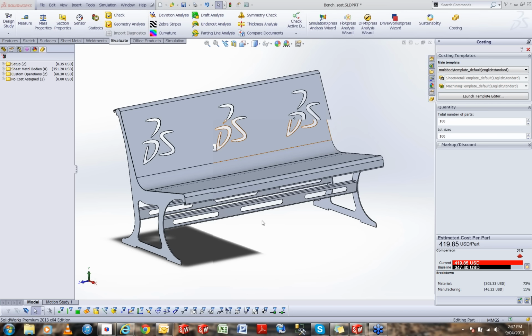So we've got a question: is the size of a design piece limited by the environment of the complete drawing? I'll take that to mean how big can you show the views on the drawing. I hope that's correct. You can set up the drawing template to basically reflect the size of your model. So you can change the scale of a view once you get it into the drawing environment. So you can show it either 1:1 or 1:5, whatever is based on the drawing. And you can set up different drawing sizes. So you can set up A3, A4, A2, A1, or any sort of custom drawing size as well. So I hope that answers your question. If not, clarify a bit further.